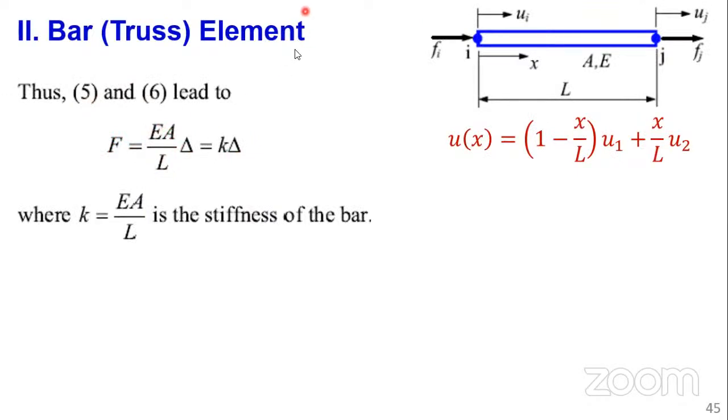So you can see, if you look carefully here, this is basically what we had before. This is Hooke's law with this part representing K. I had already explained to you that the stiffness encompasses both the geometry, which here is represented by the area and the length, and the material characteristic, which is now represented by the Young's modulus. K is now the stiffness of the bar. Of course, this one we know from the strength of materials.